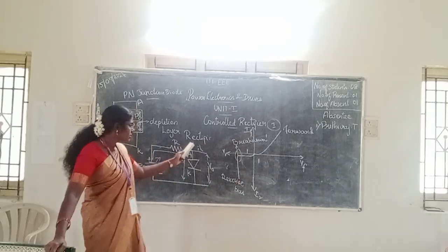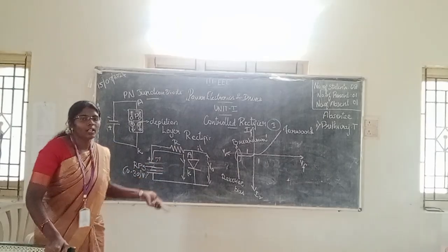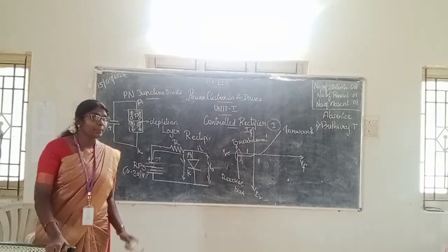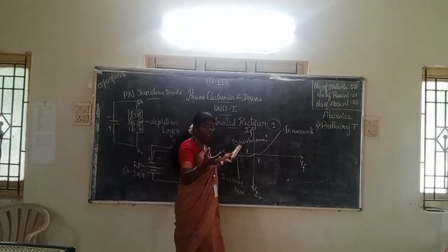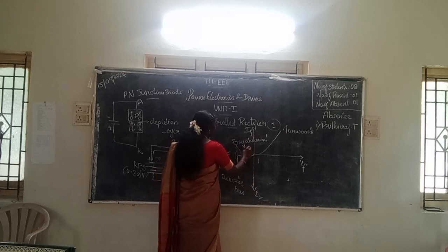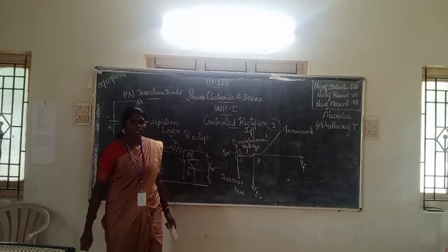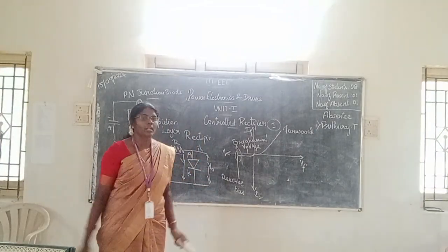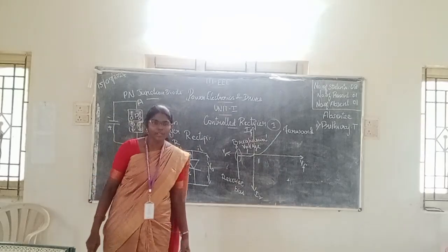During the reverse bias condition, with respect to the voltage, the current will remain the same for some period of time. It won't change. After a particular voltage rating, the breakdown occurs. That particular voltage is said to be the breakdown voltage. At breakdown, the current will get drastically increased, but your voltage won't change.